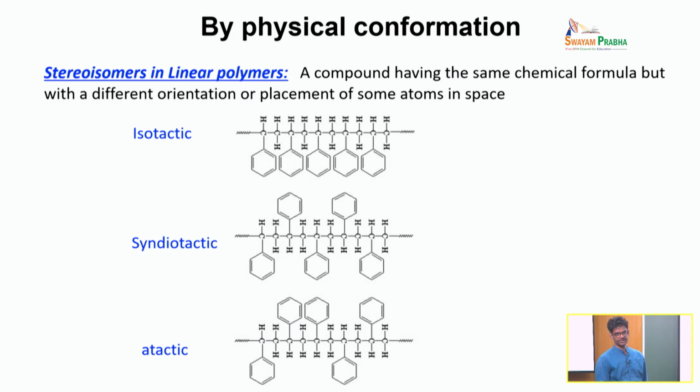You will write polystyrene polymer chemically the same, but if you look at the distribution of side group atoms, you see there is a difference, and this difference manifests in the physical and chemical properties too, in the way that they can pack, the crystallinity, the temperature resistance, and many other mechanical and electrical properties can be very much dependent on the isomer. Then there is something called atactic.